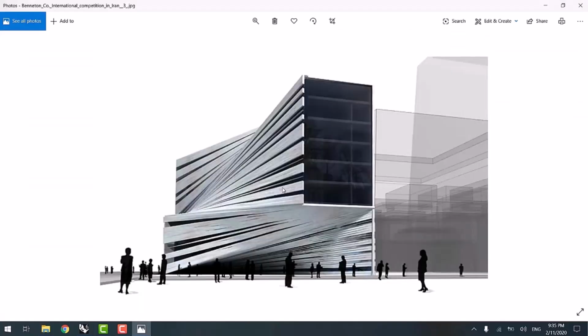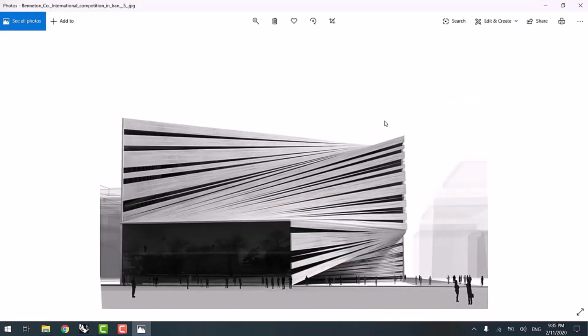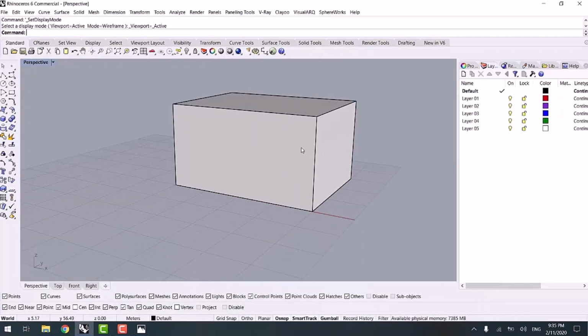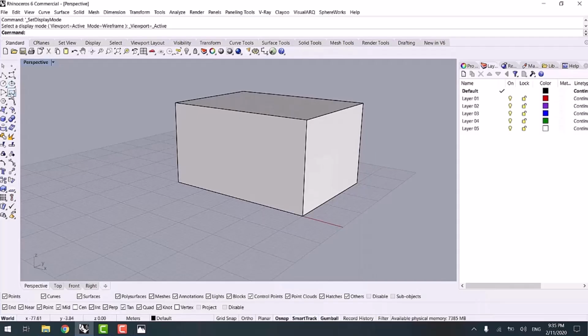As you can see in the picture, I need one rectangle on one side of our project and another one on the other side. To do so, to create those rectangles, we select rectangle, of course, and 3-point mode, the first point, and the second point's length would be 20, half of our length, and the altitude of our work would be 7 height.